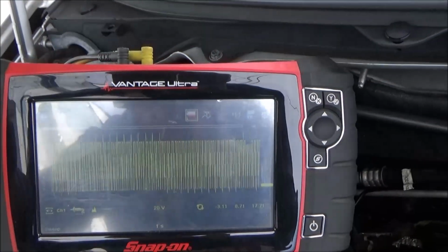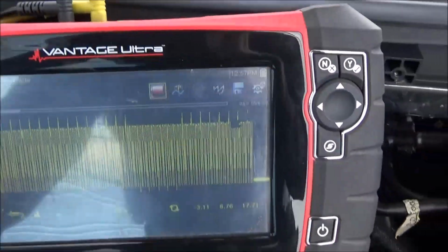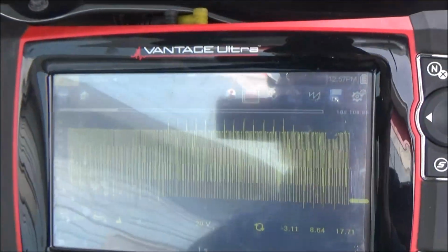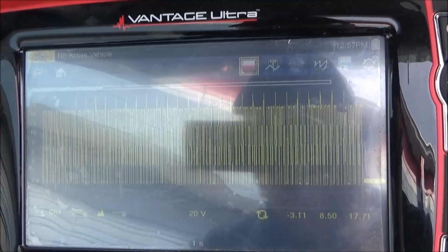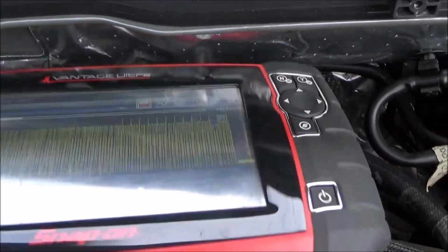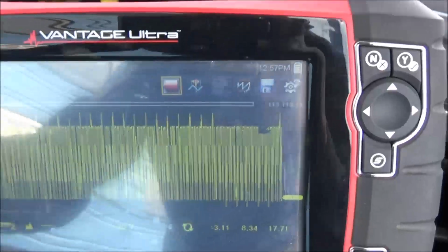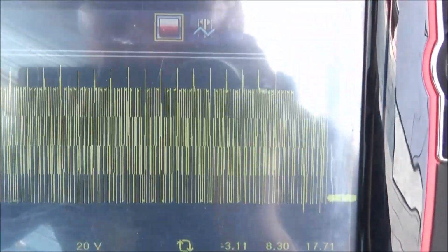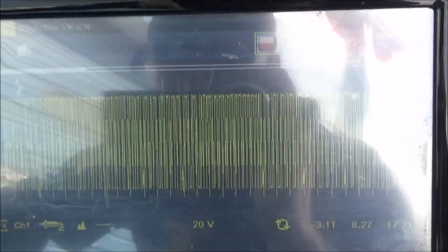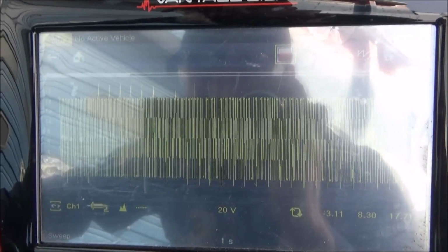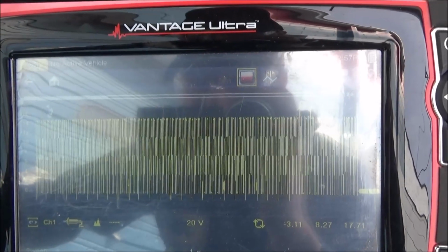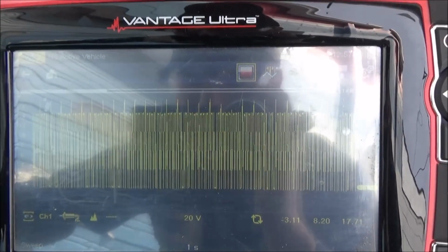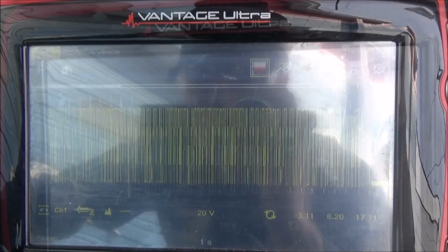And I realize it's pretty tough to see this. Maybe I can get this in a better spot. Maybe that's a little better for you guys. But I'm going to get you guys set up on a tripod, and then I'm going to run this test, and I'm going to keep you guys focused on this current duty cycle number we're seeing here. As you can see, this is basically just a 0 to 14 volt, very, very quick on-off signal. Maybe what I'll do is I'll get you guys focused in on the lab scope, and that'll kind of show you this signal a little bit better. So I'm going to get that set up and then show you guys.